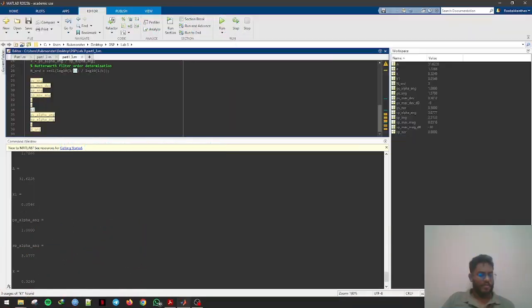Thank you very much. From here, I can conclude that the infinite impulse response IIR filter, as demonstrated in the MATLAB code, is a design for a low pass filter based on the IIR Butterworth filter approach, employing the bilinear transformation method. The code calculates crucial parameters such as filter order, frequency mapping, transition ratio, and the essential filter parameters based on the passband and stopband specification.